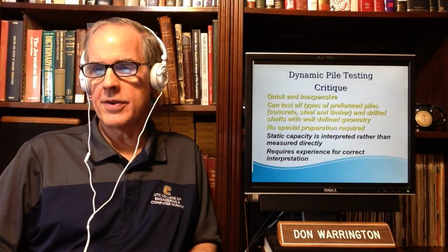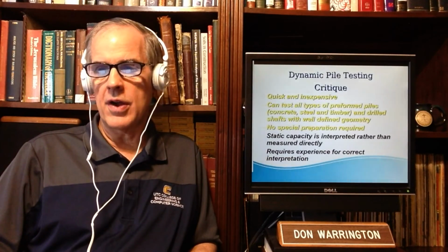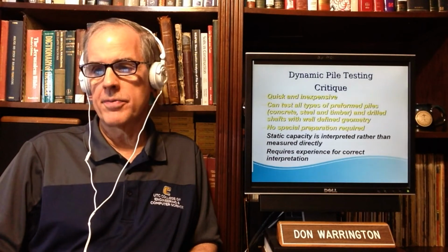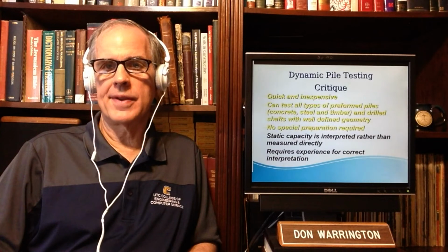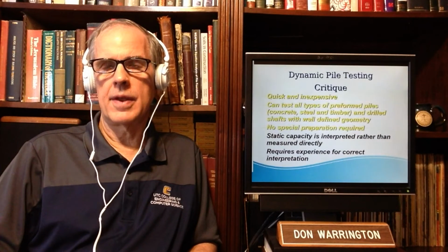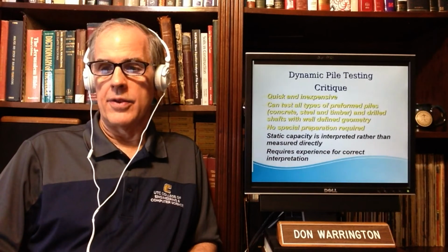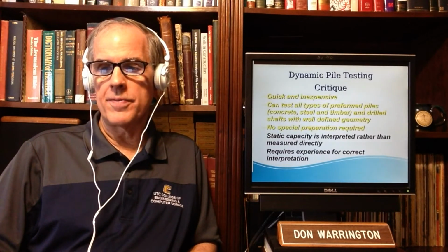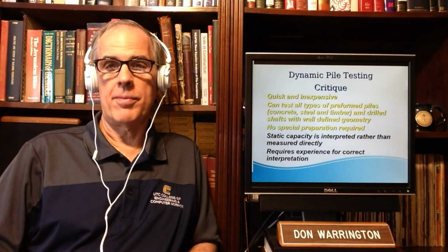Dynamic pile testing is quick and inexpensive. It can test all types of preformed piles. No special preparation of the pile other than sticking the accelerometers and strain gauges on it. The static capacity is interpreted, and it does require experience for correct interpretation. Quite a bit of it, in fact.